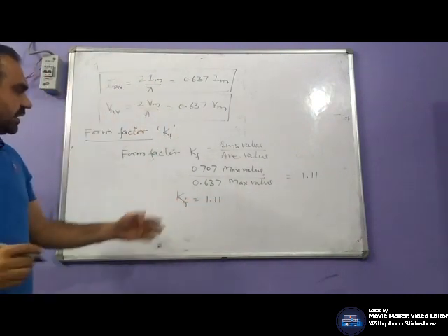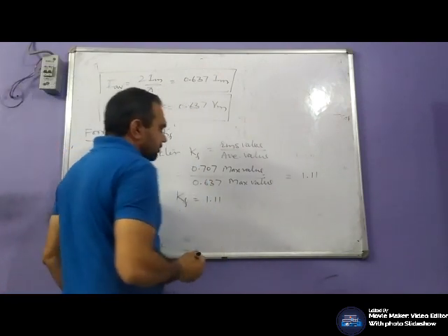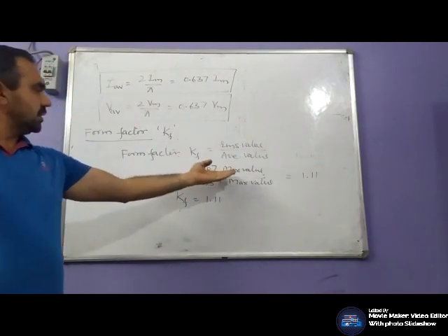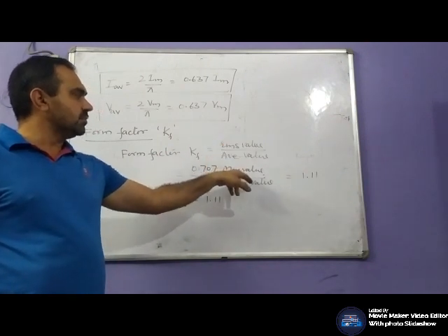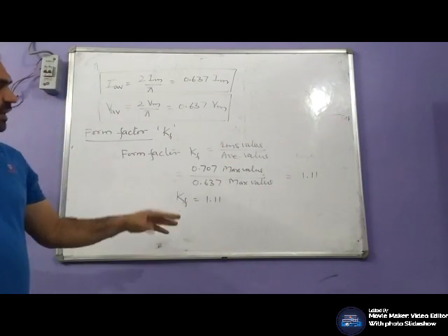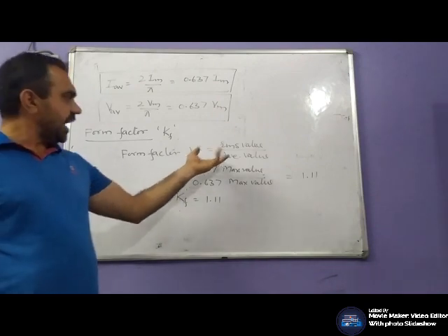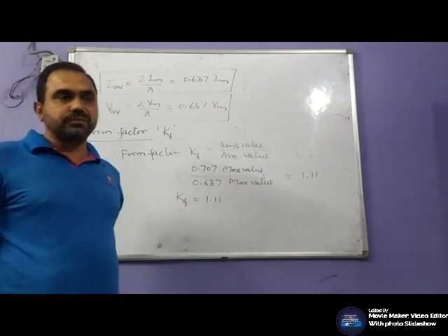Using this form factor, we can find out the RMS value from the maximum value, or we can find out average value from the maximum value.